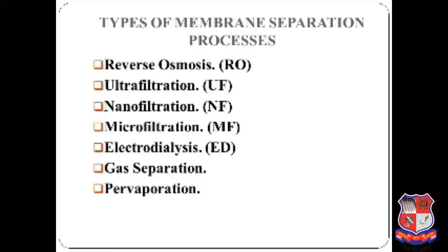Then, if you think about another separation method, membrane separation technology covers all the process engineering measures for the transport of substance between 2 fractions with the help of permeable membranes. That means, in general, it is a mechanical separation process for the separation of gaseous or liquid streams using membrane technology. According to the driving force of the operation, it is possible to distinguish different operations.